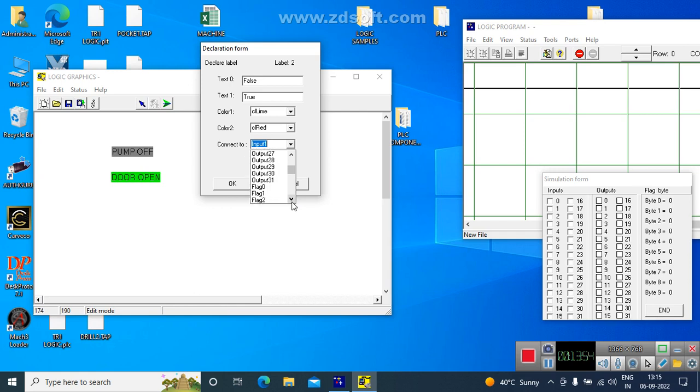These are the internal flags to the PLC which can be generated internally and used internally, which will not be in the output real world actually. So it starts from flag 0. Up to 80 flags can be generated, and then 32 counters and 32 timers. As you can see, this is a huge database and a very complicated program can be made.